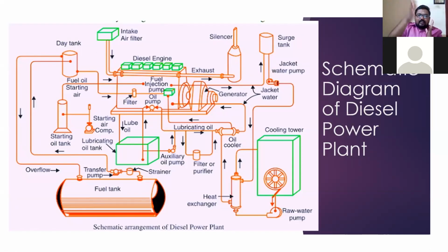So automatically, that will be flowing like a snake, and the water or the coolant will be flowing through that path, and the heat transfer will be happening from your cylinder head to this coolant or the water. Though when it is coming out, it will be too hot and the pressure will be very high. So that is why first itself I'm placing one surge tank.